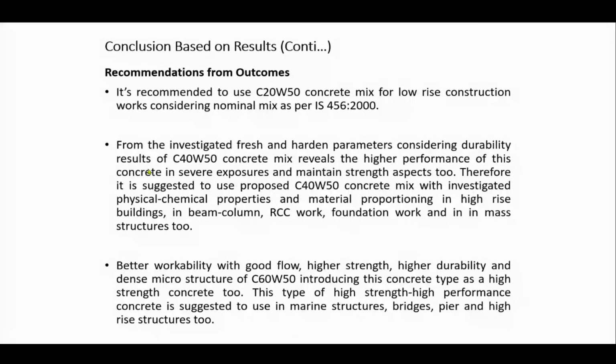Now, from that steel industry waste, utilization in the construction industry as concrete manufacturing. What is the recommendation from the outcome? We can say that it's recommended to use C20W50, meaning 20 grade of concrete having a 50% waste replacement in the concrete mix for low rise construction work, considering nominal mix as per IS 456 2000.